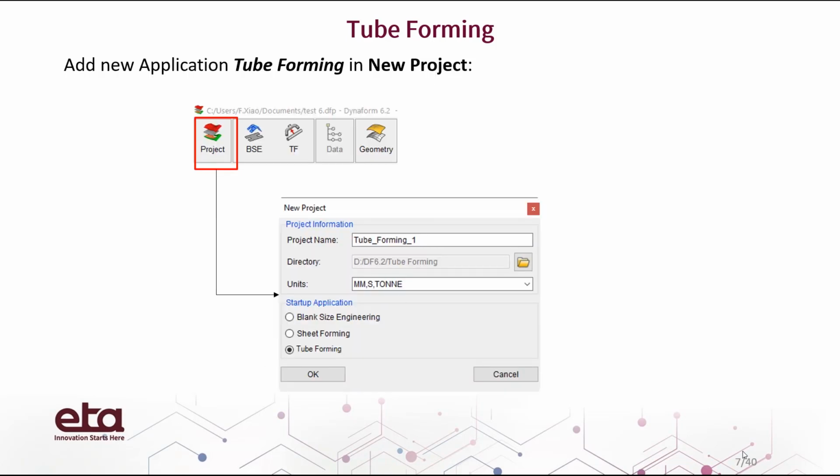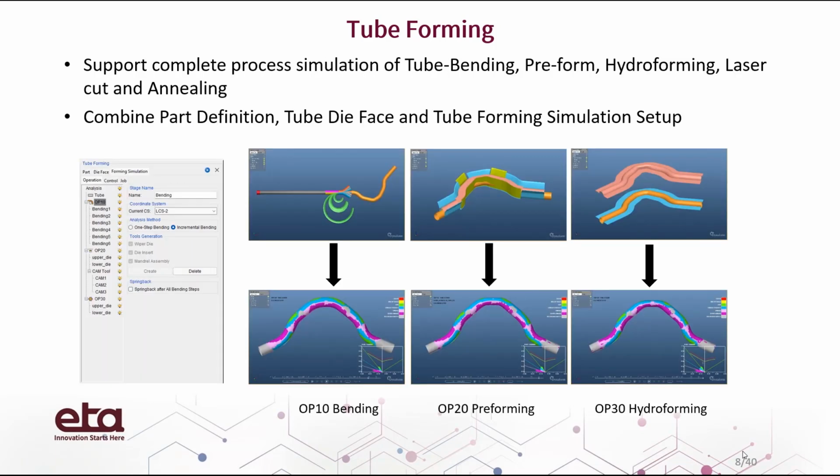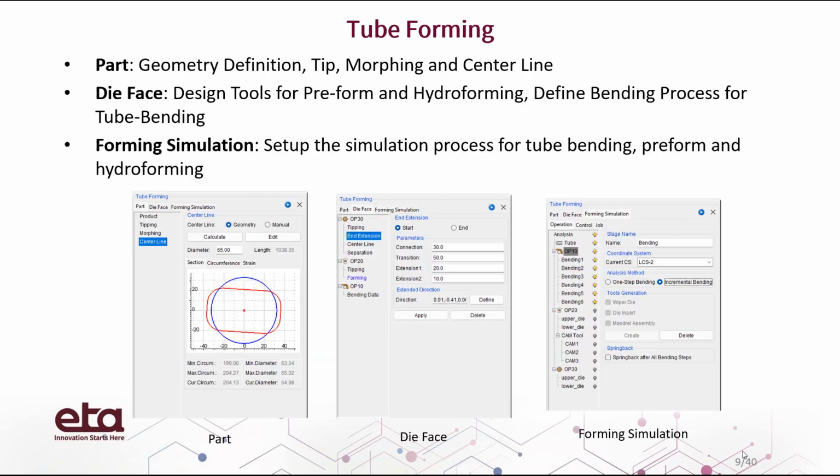As illustrated here, the tube forming application is included in Startup application. Tube forming fully supports tube bending, preform, hydroforming, laser cut, and annealing with tools for part definition, die face design, and setup of forming simulation. Here is the graphic interface of part definition, die face design, and the forming simulation setup.